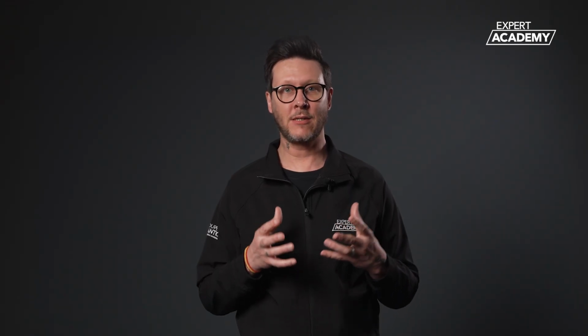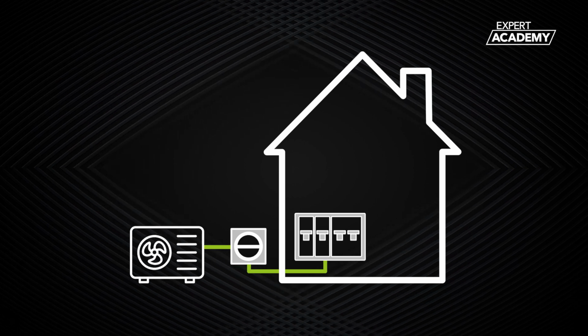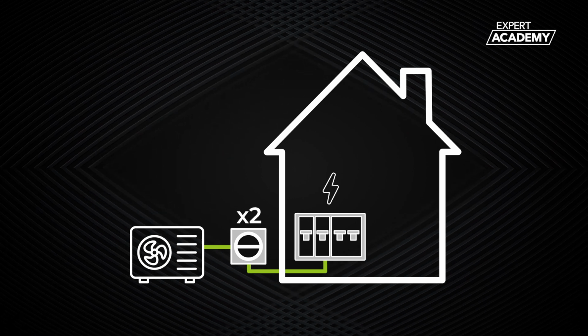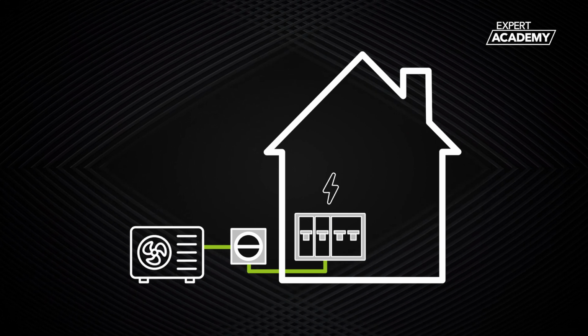An adequately sized and protected electrical cable will need to be run between the main electrical panel in the property to the rotary isolator next to the heat pump. An electrician should determine the cable size. Some heat pumps may need more than one isolator for different components. The Logic Air only requires a single isolator.